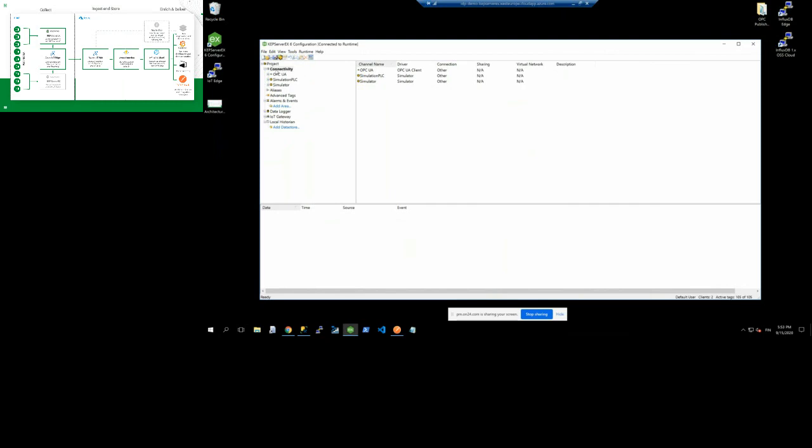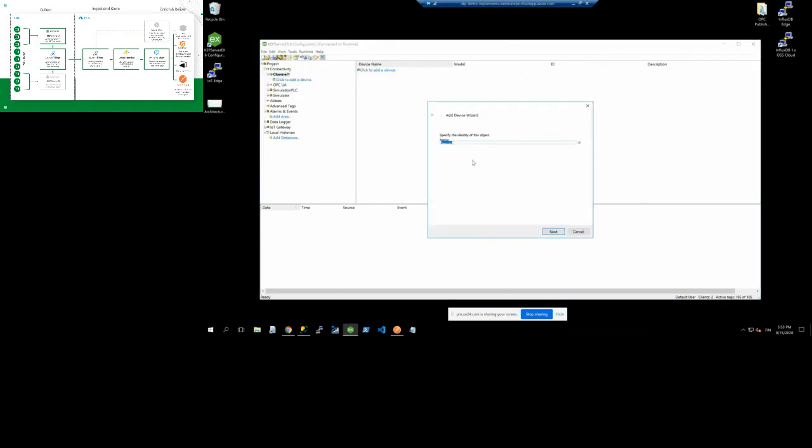So basically what we have here is the ability to create a new channel, and we can pick and choose the device type we want to connect. Coming from Europe, I would say 90% is Siemens, but it can also be Allen Bradley, Honeywell, Rockwell, whatnot. Then we connect to the device, and then we just create our OPC tag configuration using some configuration parameters.